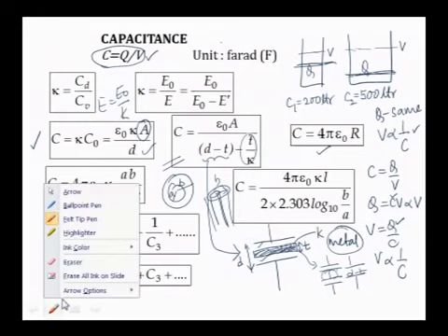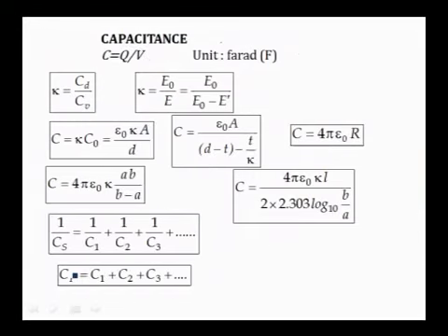So then going further to series and parallel. In case of series, remember it is similar to resistances in parallel, the nature of the equation. 1 by Cs goes as sum of reciprocals, and therefore Cs will be less. When you put the capacitor in series, the value decreases, and if you put n equal capacitors in series, Cs will be C by n. So that is an important thing to remember.